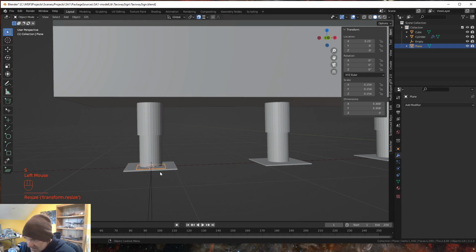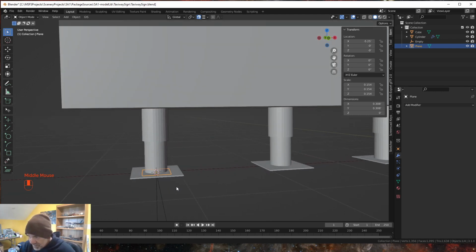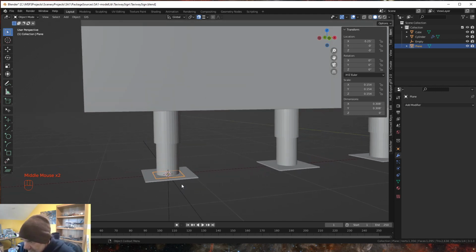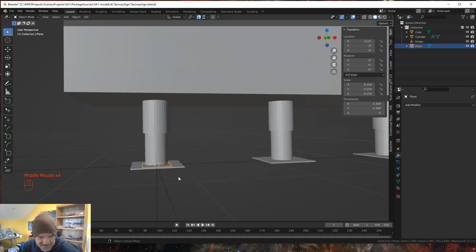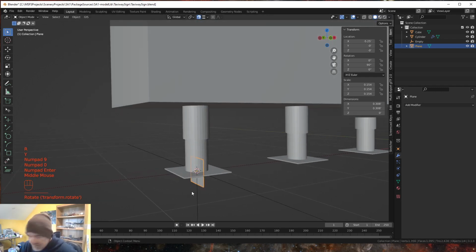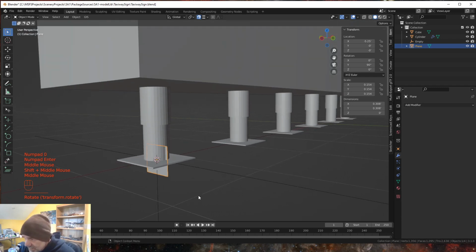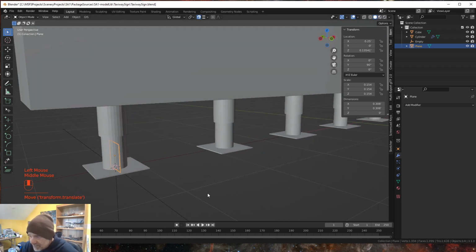And notice that it is not being arrayed because I don't want it arrayed yet. Alright, now I want to rotate that on the Y. So I'm going to rotate Y 90 degrees to stand it up. Okay, and then let's see, G Z. We're going to bring that up until it's right there, okay?